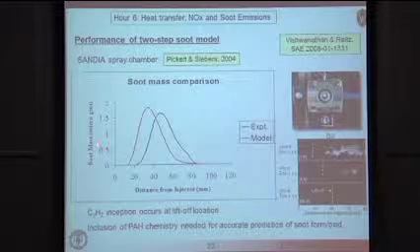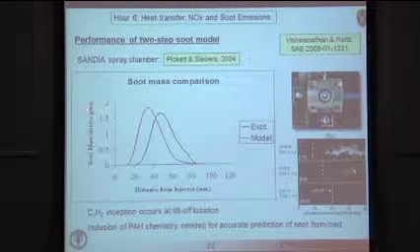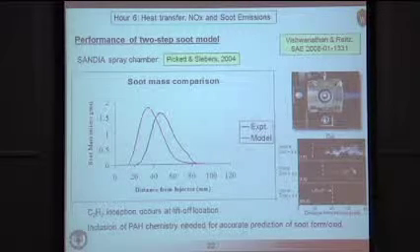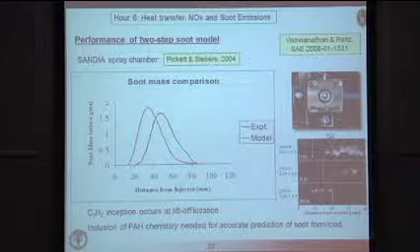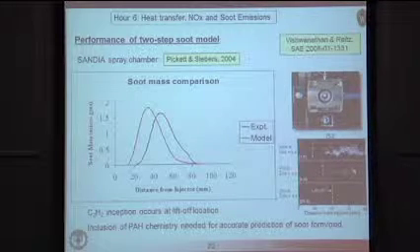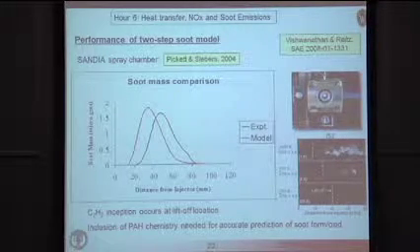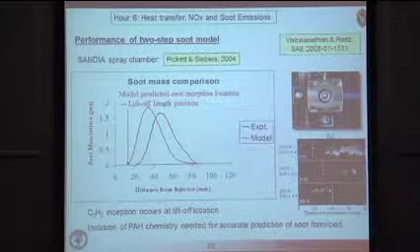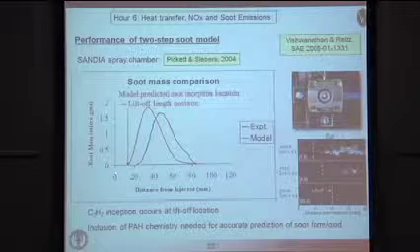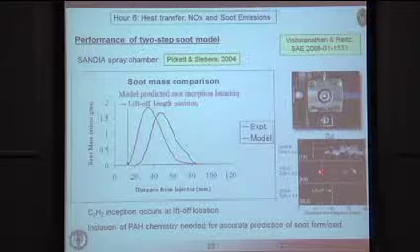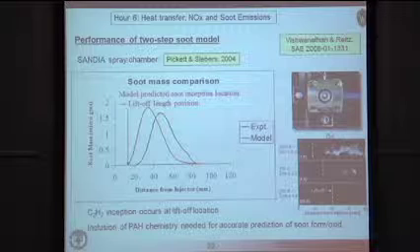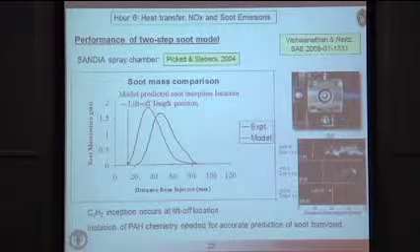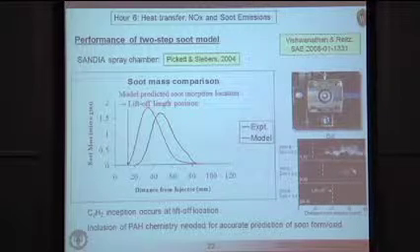And what they find is that the soot mass, here in micrograms as total soot mass as a function of distance from the injector, this black line, looks like this. You form the soot, and then you oxidize the soot. When we use the two-step model, we get this result shown in the red there. And basically, the model essentially says the moment you get some acetylene, you start forming soot. And that occurs right at the liftoff length location. And so there's a qualitative disagreement, even if you tune the soot model to get roughly the same magnitude.